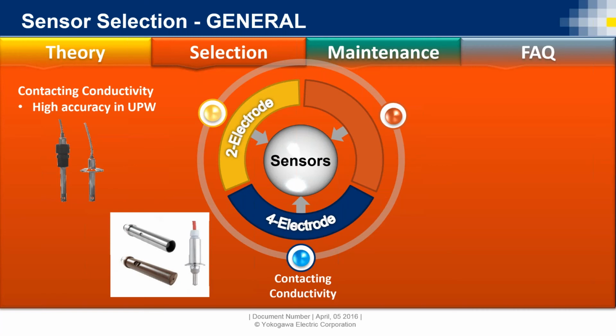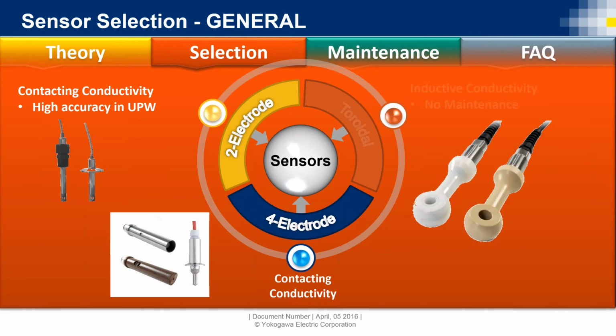Another style is this one here, the Hamilton one. You can kind of see it on here, but it has the PEEK material at the bottom, and then it has a metal pole. On this side we can only see 2, but on the other side there are 2 more. So those poles are the same thing as what would be inside those other sensors, that have the ions that respond and react, so that we can generate and read the voltage that's generated.